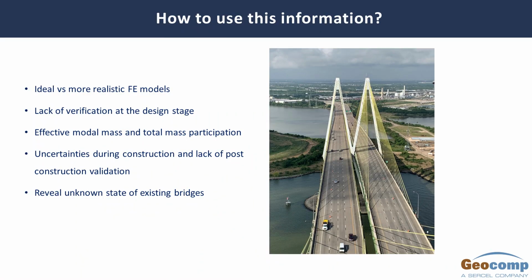Now, okay, enough with the wizardry, how can we use this information? One of the ideal ways of using this is creating more realistic finite element models. I totally appreciate that for typical, simple bread and butter bridges, single span, short bridges, you may really not need to do any kind of this study. But for longer bridges, for bridges that are high risk especially, it would be valuable to look at your finite element model and see if the response of your model is actually aligning with what we are observing in the field. Whether you choose to do a manual calibration or an automatic calibration, there are some methods to do that as well.